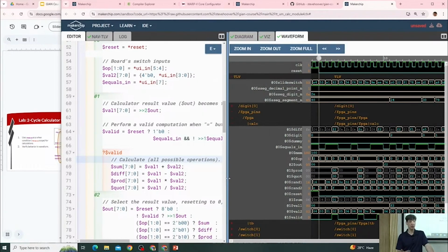Since we are using a two-state simulator and the current mechanism for checking of the when conditions is don't care propagation, we don't actually get that checking. So, in its current state, you can have errors where you're consuming things that are invalid that you shouldn't. But at least the theory of the feature is that you would get checking that would ensure that you indeed don't care about these values.